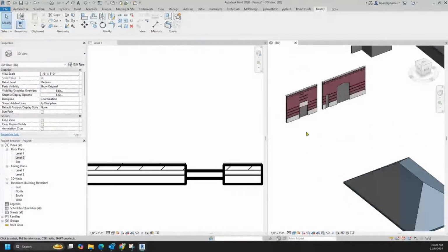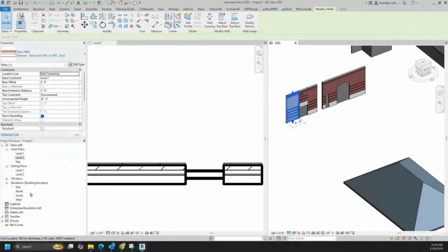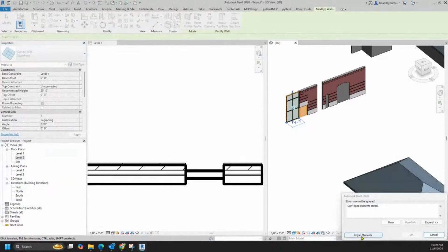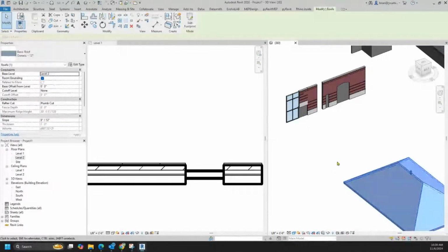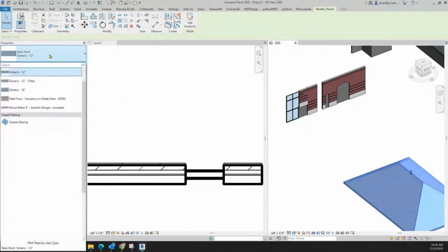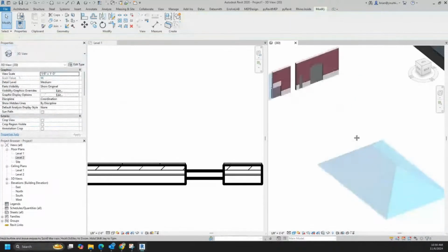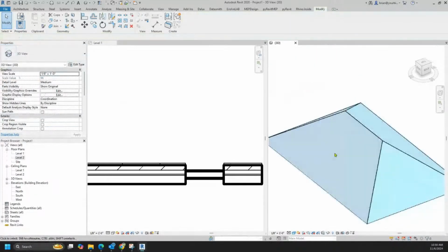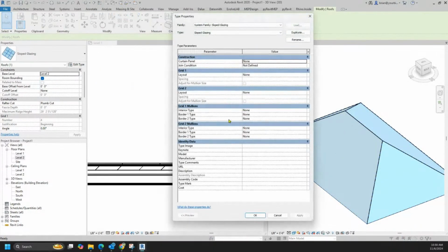What a lot of people don't know is you remember how we could take this wall right here and we could turn this wall into this storefront. And it's like, oh, cool. Now it's windows. Well, guess what? With a roof, it's called slope glazing. And once you do the sloped glazing, if you remember, we could put rules in it. We could say the layout one is a fixed distance, and I want 5 foot.